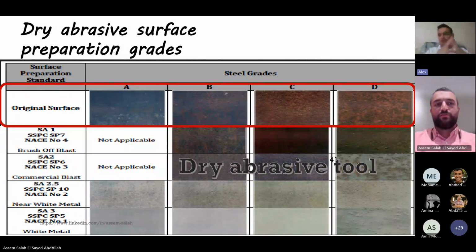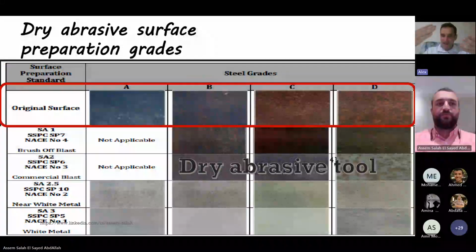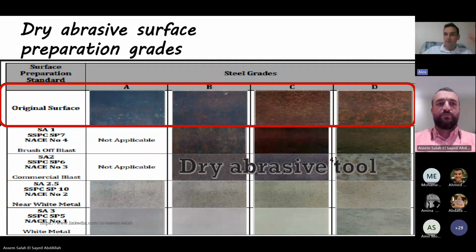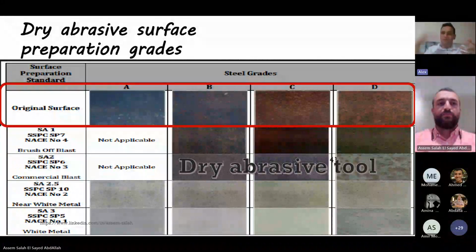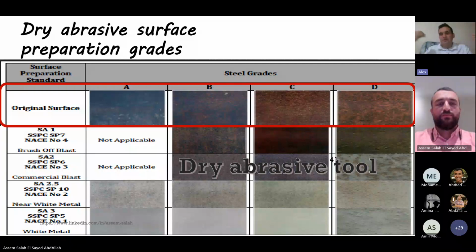I mean, because we didn't tell about this. Maybe we must get back a little bit and say that removing the mill scale in our industry is very important, is very critical, because mill scale, as you saw in the photos about the weathering, falls down with time, and if you just apply any paint on mill scale, it will fall down with the mill scale throughout the time. I mean, in 3-5 months, it will just fall down with the paint. So if you didn't remove it, you would not receive a good result. You will have corrosion in a very short term.